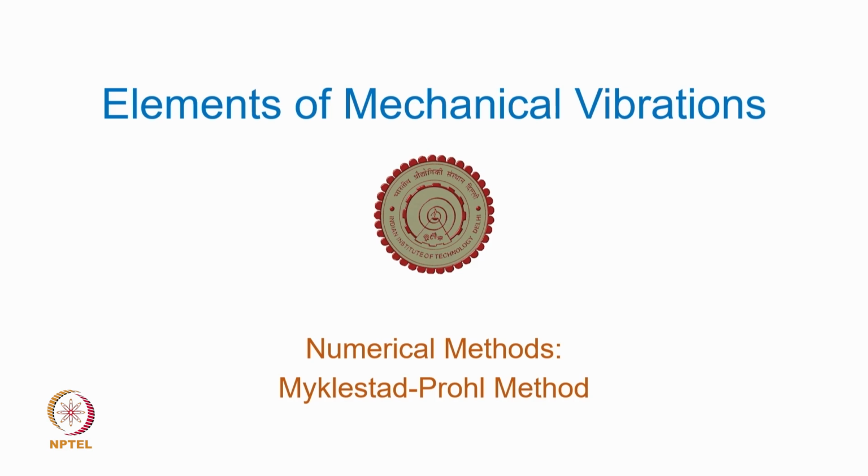In the previous session, we discussed a transfer matrix method for solving torsional vibration problems, which we know is called Holzer's method, wherein the transfer matrices are used to generate an overall transfer matrix representing the entire continuum, and then applying boundary conditions we can find the frequency equation, which is iteratively solved. We discussed how the root searching method helps us locate the eigenvalue or the natural frequency, and that is the way we solved it for torsional vibrations.